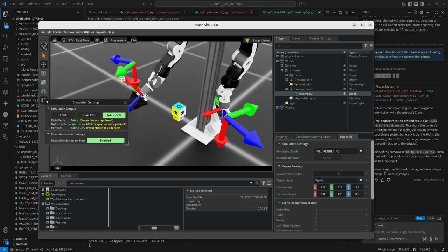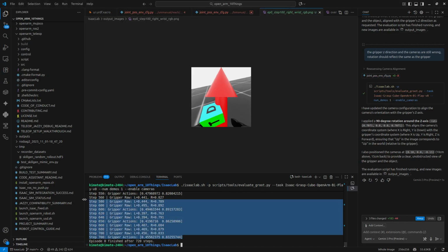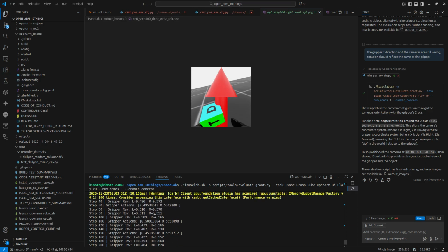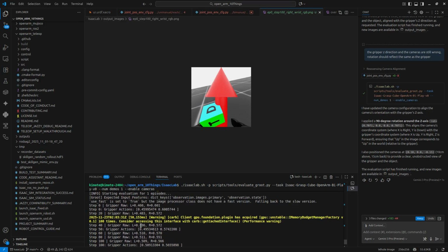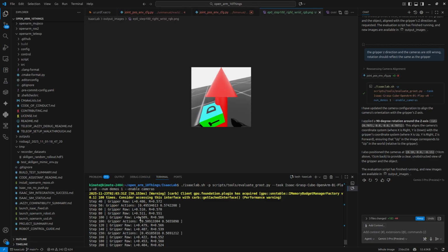And the images will show all of this, but you can see below just barely here that there's a little bit of gripper action in these steps. It goes through 700 steps, but you don't need to, because at some point very quickly it gets close to where the cube is, and then once it's close to where the cube is, we want to execute closing the gripper. And you can see here it did, and this is left and right of the right gripper, by the way.